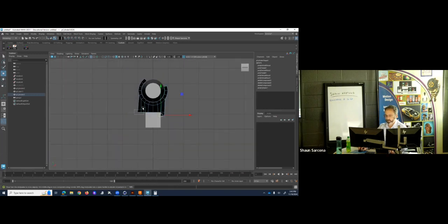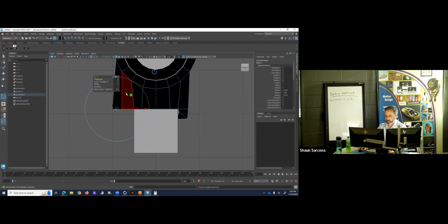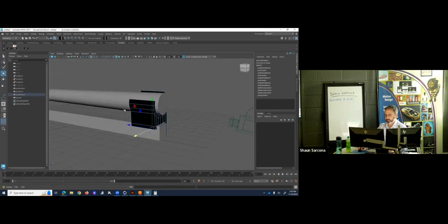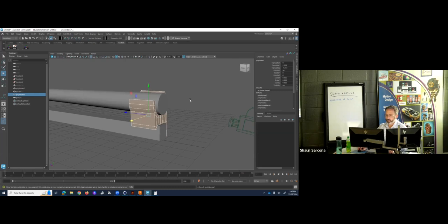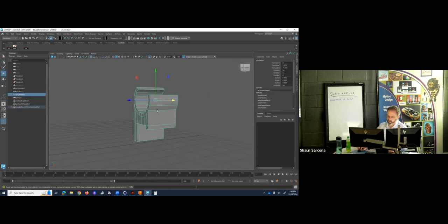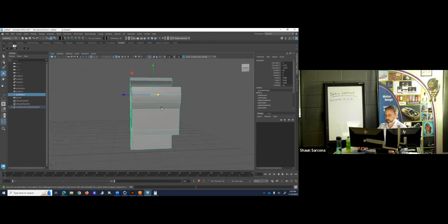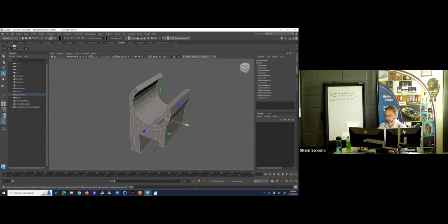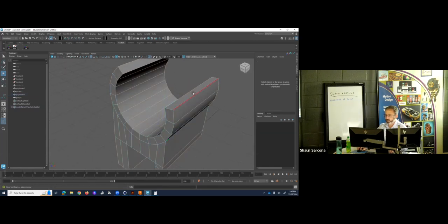And for the other side, I'm going to do the same kind of thing, just extrude this, but this time I'm just going to pull this straight down. I need a little bit more room on this side, so I'll move this over some. The reason it's dark is because it's inside out, so I'm going to reverse it. Now it's not. Okay, so now I just recreated that other piece on here. It still needs bevels and stuff, so we'll grab everything again. Actually, not everything. I don't want these pieces selected.